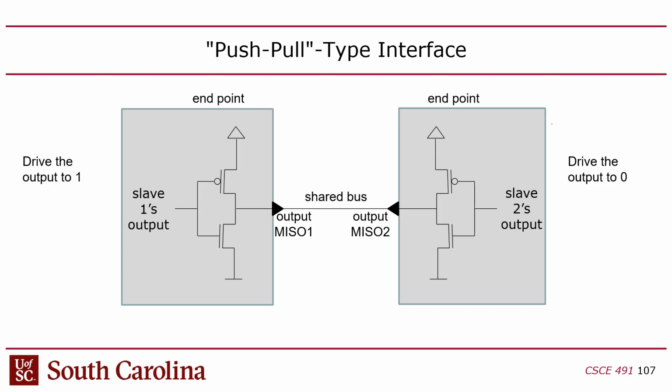It creates a low impedance path from VDD in one chip across that wire and then down to ground in the other chip. So you have a path involving two chips that allows current to flow from the power supply of one chip, gets dumped out, and sinks into the ground of another chip, right? And so that's called conflict.